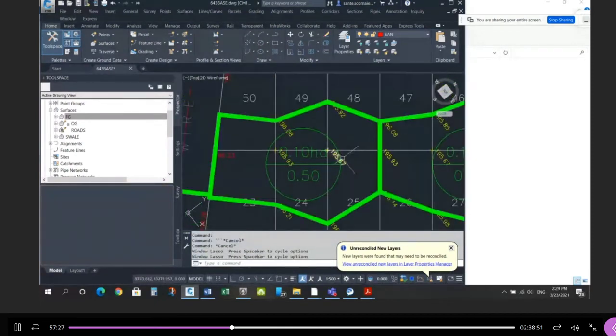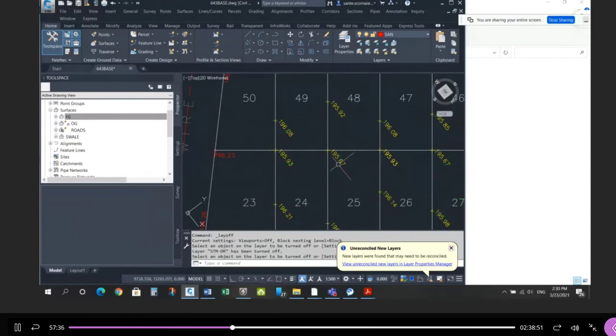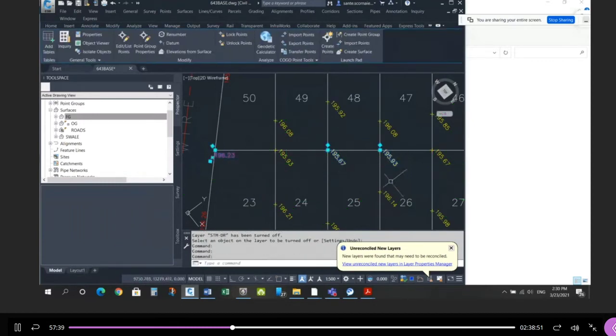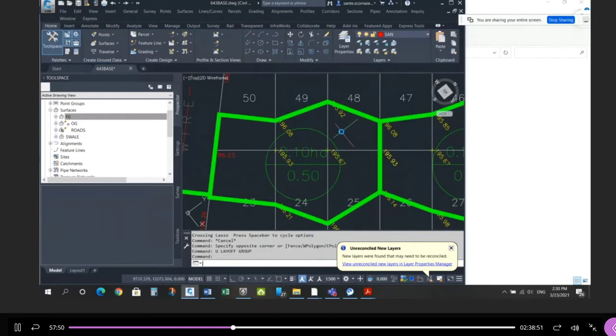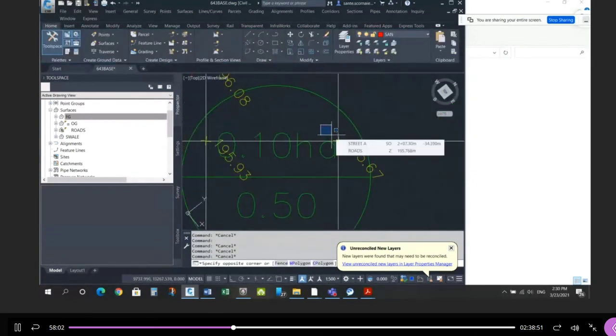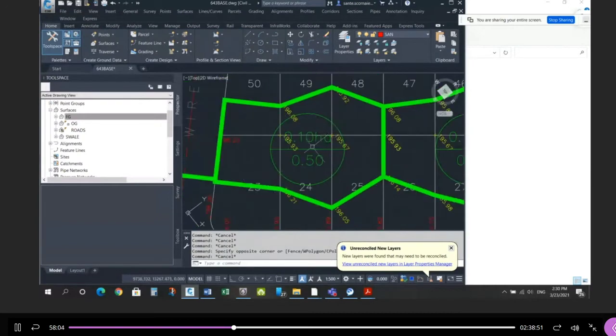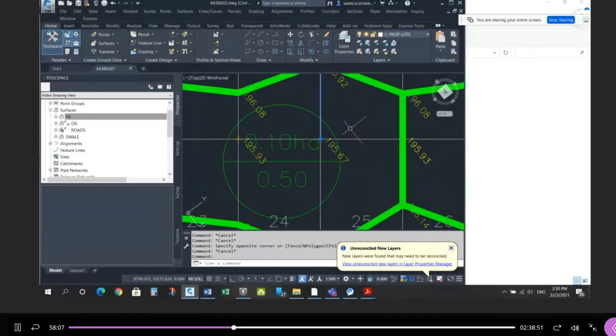And then the thought is, okay, how many lots are draining? So if you look at this, let's take this away. Here's the low point, here's the high point, here's the high point. So I have these backyards, and these backyards draining to the low point, and I have these backyards here draining to the low point. Let's turn the drainage areas back on. So 1, 2, 3, 4 backyards draining to this point, and then from the other side, 2 backyards draining to this point. So I would put the catch basin here and prevent all this water from crossing this property line.